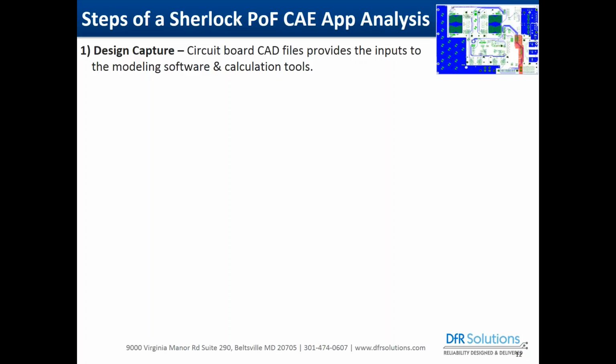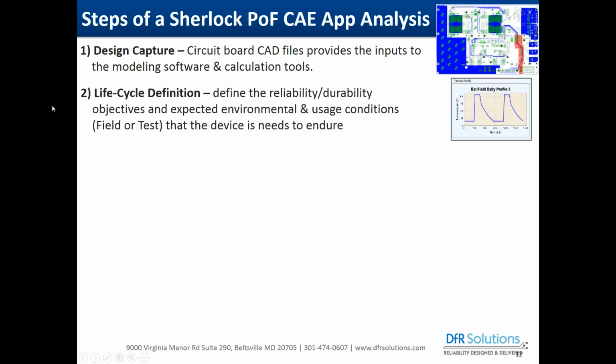And we then take the parts list and correlate that with a built-in library of all the different component models, and we use the circuit board pick-and-place build file in order to say each component goes at this location and is connected to these solder pads. And that's how we create a rapid 3D model of your specific circuit board design for your electronic product.